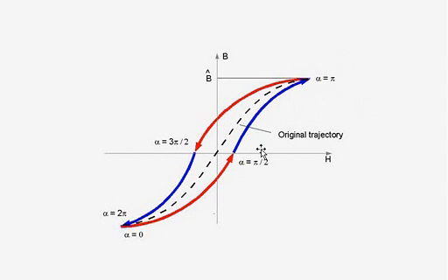The method I chose was to use what's called the Steinmetz function for core loss in a magnetic material, which, according to my reference, he did some tests and showed that the Steinmetz function fairly accurately replicates the core loss. So I used the curve there called original trajectory.